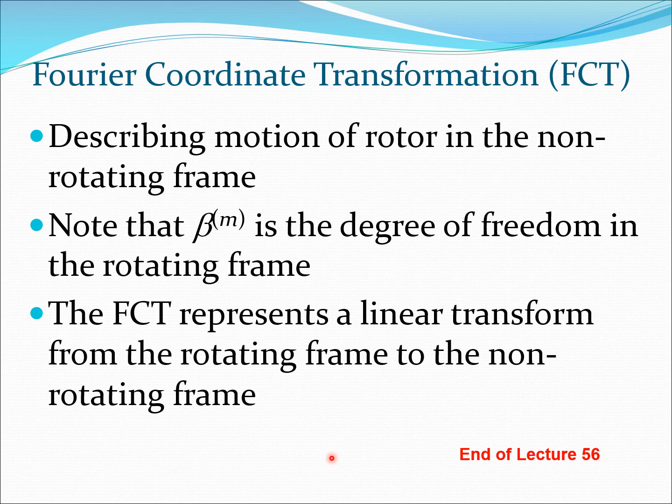So this particular transformation which I discussed in the previous slide is known as the Fourier coordinate transformation, and it's very important in helicopter dynamics and rotor dynamics. Essentially, this helps us describe the motion of the rotor in the non-rotating frame, which I mentioned becomes very important if you want to develop coupled equations later on.